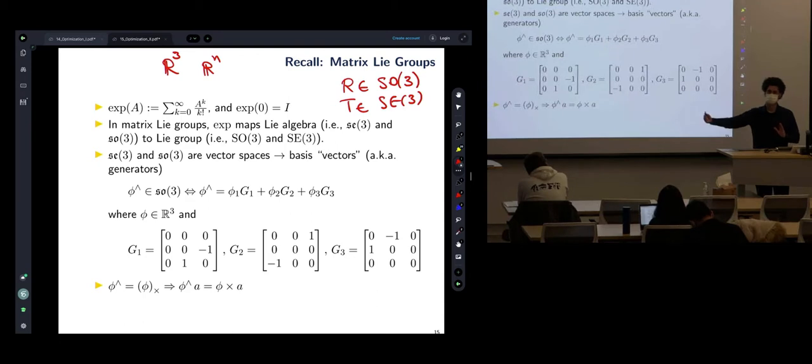You process data, you move forward in time. The more accurate your model is to integrate and move forward, the better results you get. We will never go back in time to correct previous estimates. So the filters are less forgiving because of the lack of looking back at data and reprocessing data. The performance of the invariant EKF as opposed to extended Kalman filter showed us a big difference. So luckily in optimization, things are a little nicer. And we'll see why.